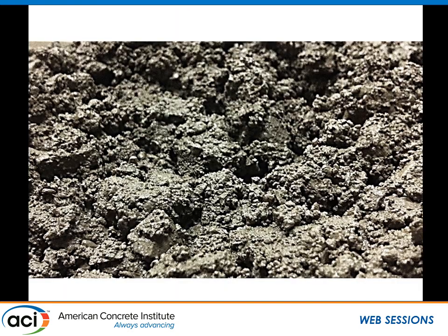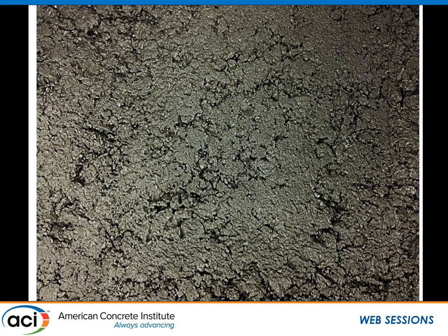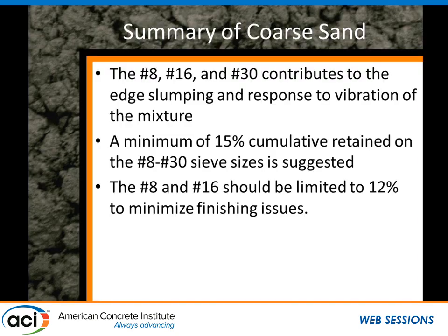Okay? When you actually go to finish these, to beat them down and finish them, you just can't. It's tough. They actually tear across the surface. You cannot have too much of these coarse sands. You cannot have too little of these coarse sands. You need to be in between.